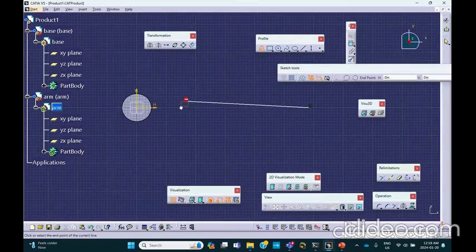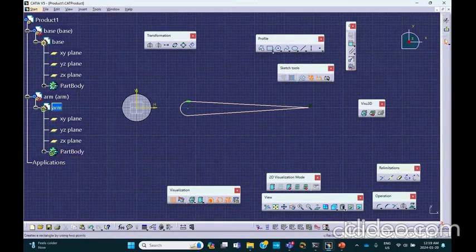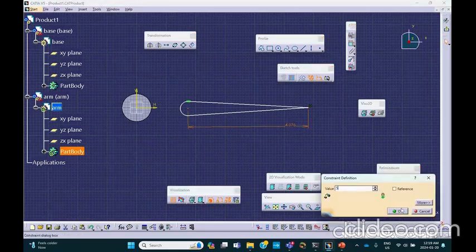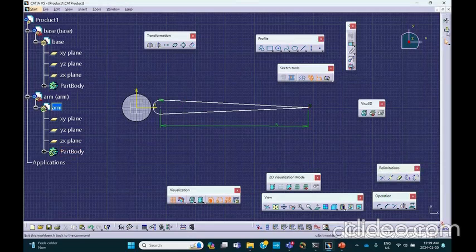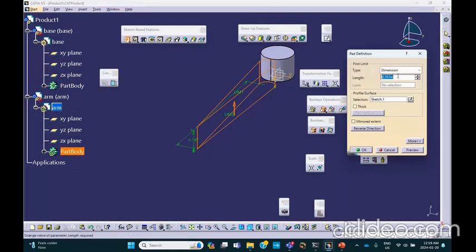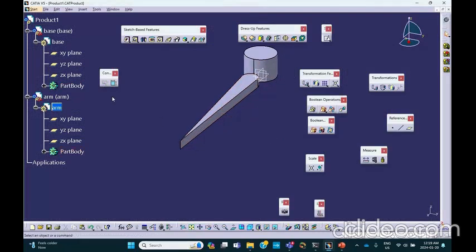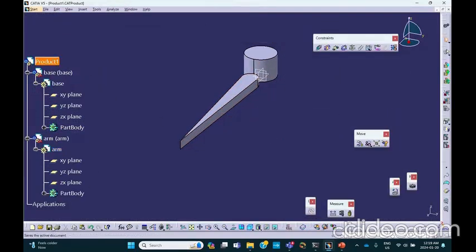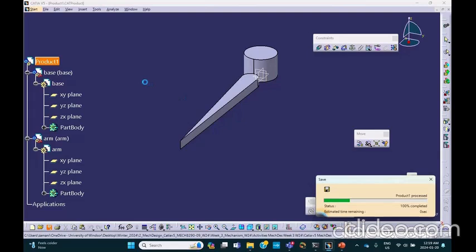So probably something like this. The actual shape of it doesn't matter that much, but this distance from the center to that tip should be 5 inches. Five, we say okay. All right, exit. And we're going to pad this. I'll use point 3 there. So all the way to the top, click on the floppy so that everything is in that folder now.